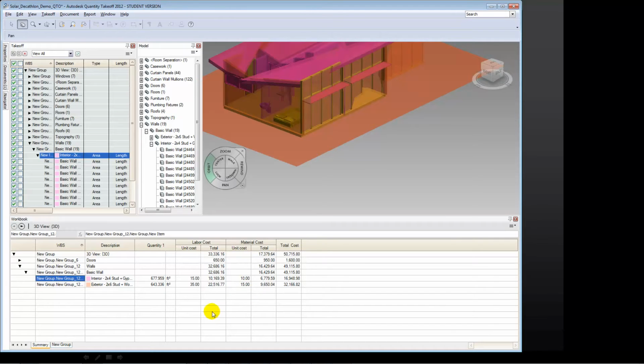So how that works now is, if the quantities are here and it turns out that we need to change something, for example, you find out that for those interior walls, it's not going to be $15 a square foot, but something like $25 a square foot, I can just type that in there, the number will multiply through, and it will roll up into the new revised cost.